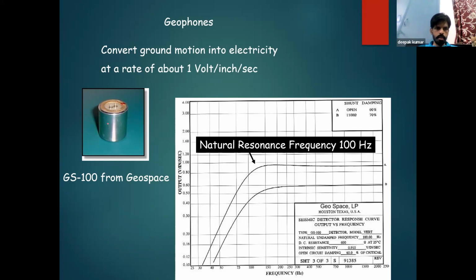Inside that we see this kind of structure attached to the top of it. Suppose this is my top layer of the geophone, the plastic layer. This particular thing will be attached to the top or the bottom of that geophone. It has a magnet, and that magnet is surrounded by a coil. Are we familiar with the concept of electromagnetic flux?